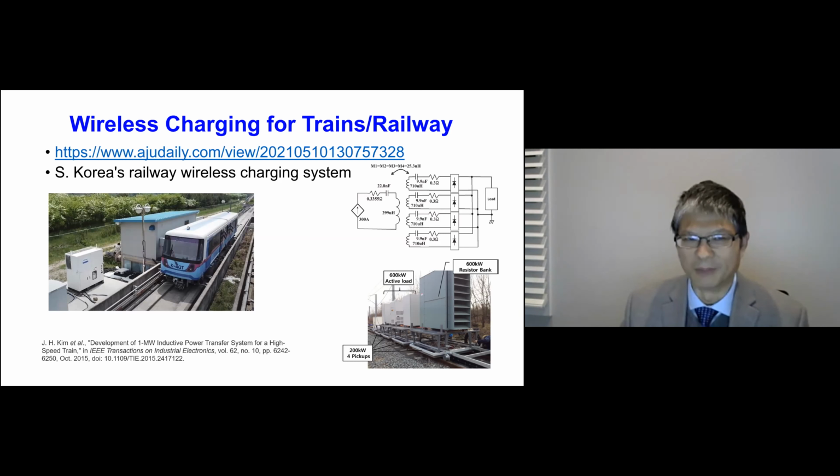Right now, we have to build a much bigger tunnel than the vehicle needs, because we have to have the overhead pantograph to transfer power. That cost itself can be very high. So if we build some sort of wireless power in the tunnel, which doesn't take much space, we can reduce the tunnel size by 1/3, which means a humongous cost reduction.